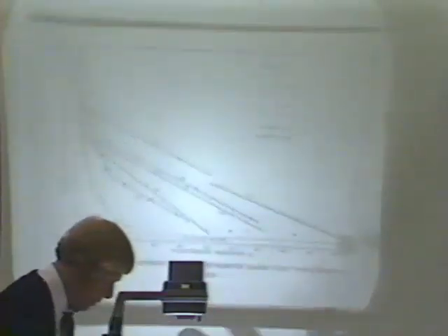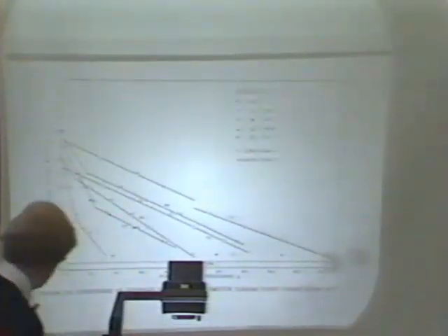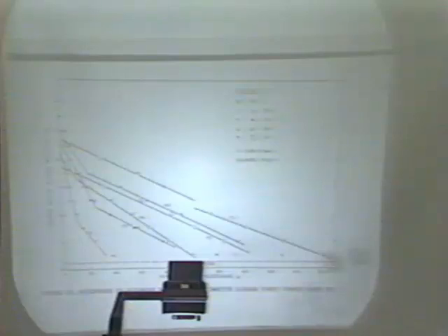You have a hard time seeing that amount of swelling. I just want to point out again that there was this change that we attributed to crushing of the aggregates, and that these curves all moved upward, indicating greater strength, greater resistance to penetration, some kind of change in strength with time.